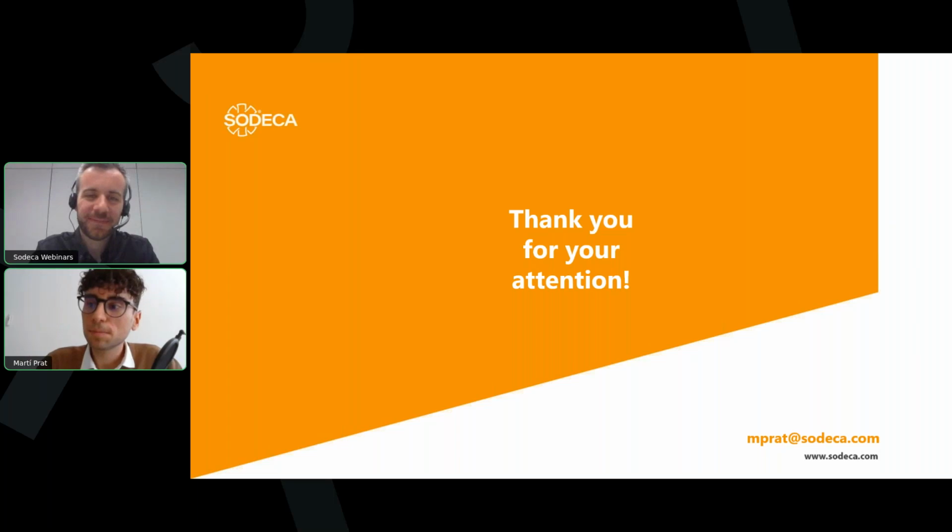Well, actually, it changes in case we have natural ventilation. In most of the standards, for instance, in the Spanish standard, there shouldn't be any distance larger than 25 meters from any part of the car park to any opening.